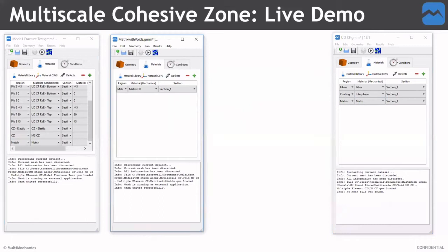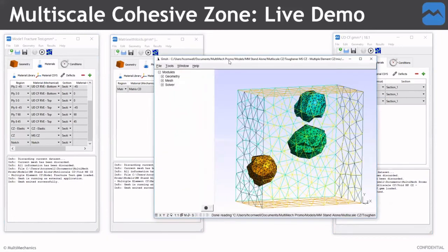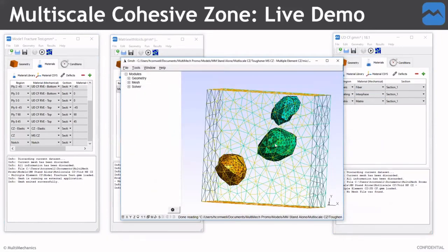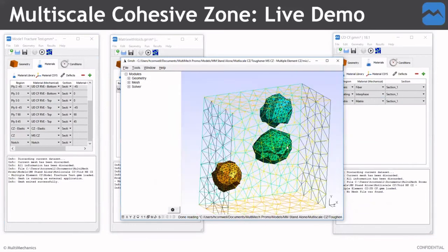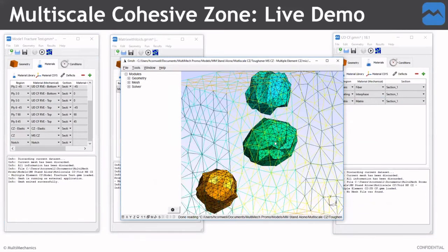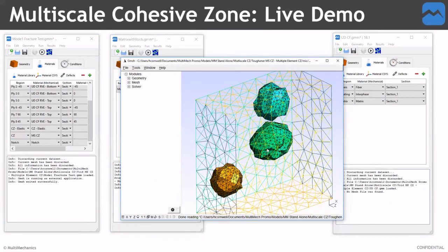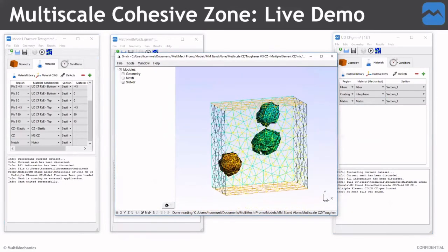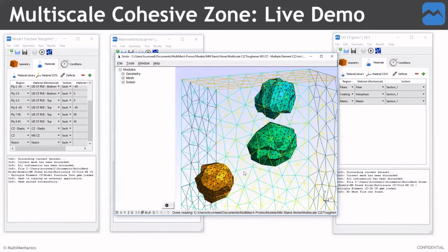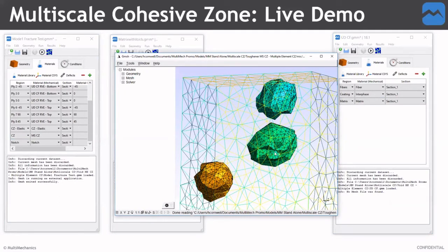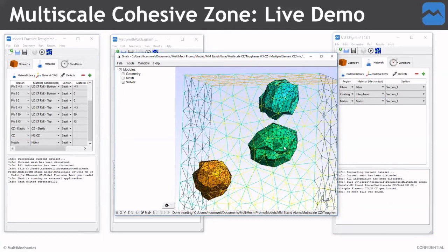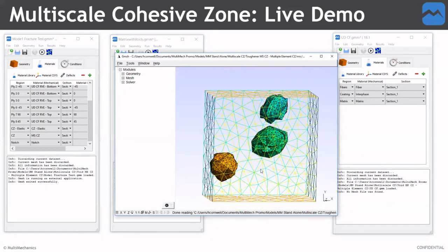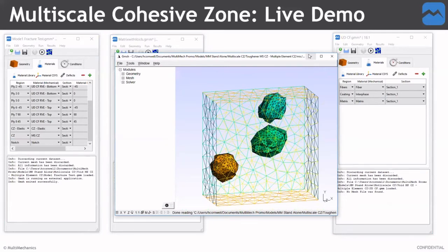The next microstructure we'll use to represent the cohesive zone is a toughened interlaminar region. So we have the same kind of matrix, but instead of voids, we will now have particulates that have a higher modulus, which are a lot of times used in interlaminar regions to help toughen against crack propagation, and help make the crack path a little more tortuous. So we'll see how this affects the overall fracture energy and factor within the simulation by using this microstructure.